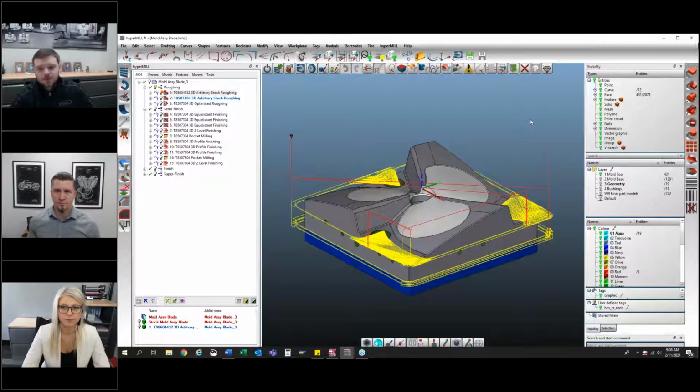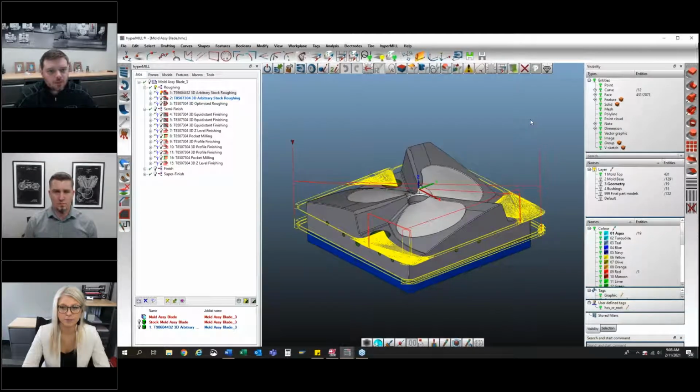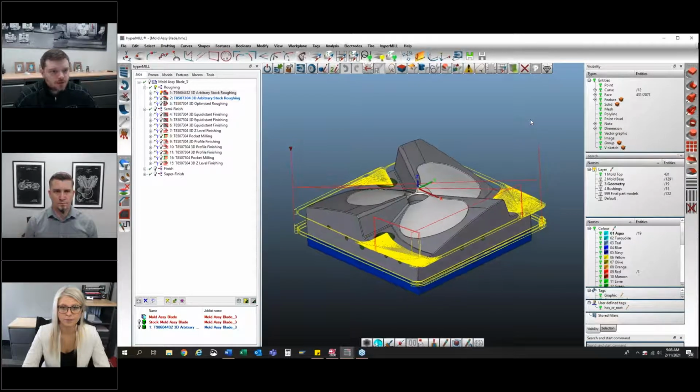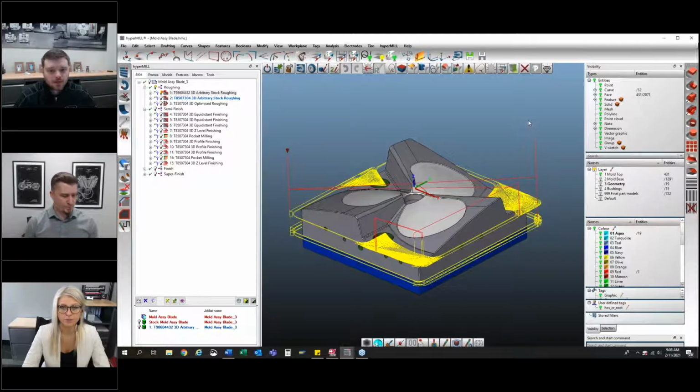Okay, so this first part here we made out of D2 tool steel, heat treated to 60 Rockwell. This is done in hyperMILL, so all of the dynamic milling is a volume mill add-on within their software. The first operation that we chose was with our HX NVS, a 3/8 tool, just to get the bulk of the material out as quick as possible.